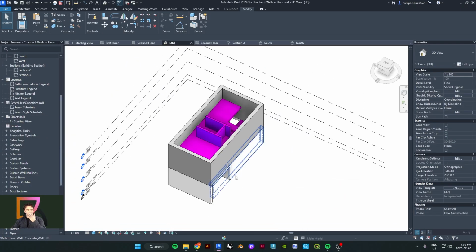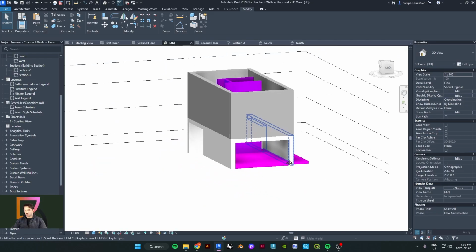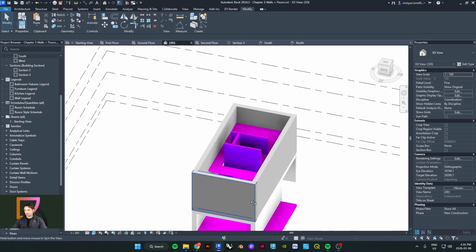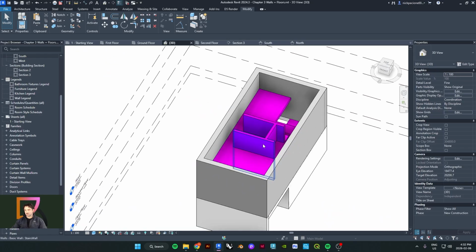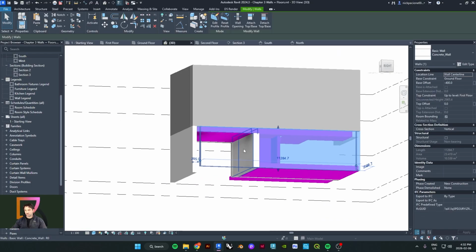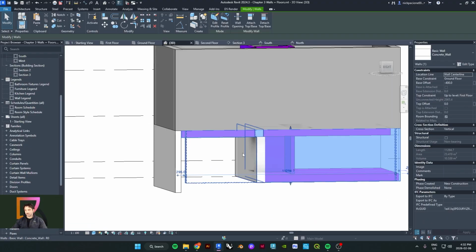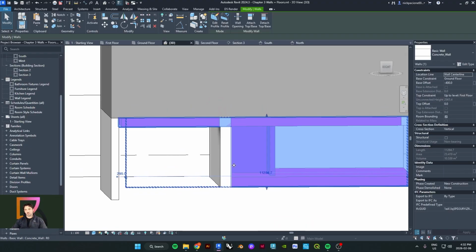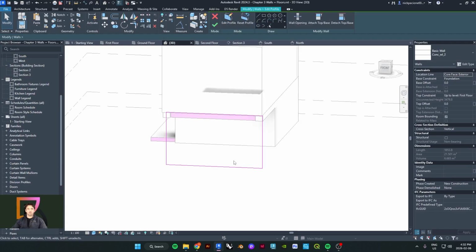Okay, so what I've gone and done is I took the liberty to accurately finish the wall assemblies. I've done the floors using the previous strategy above, editing the boundaries. And what I've done for these walls is, because they stretch across the floor like this, how this functions is a profile. Walls in Revit have the ability to edit their profile.